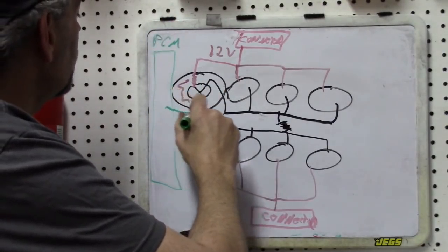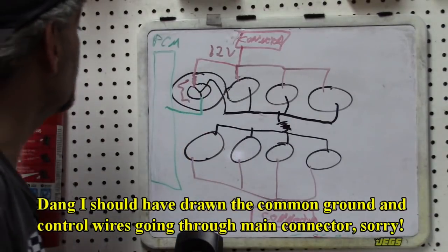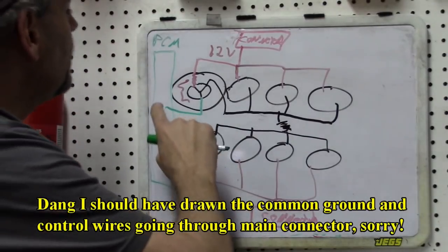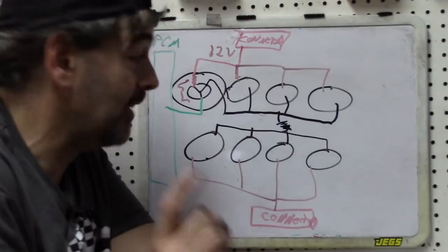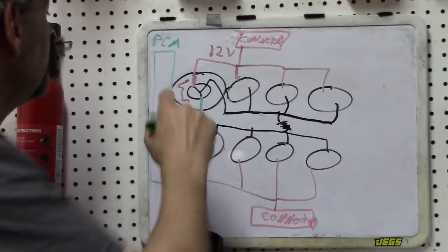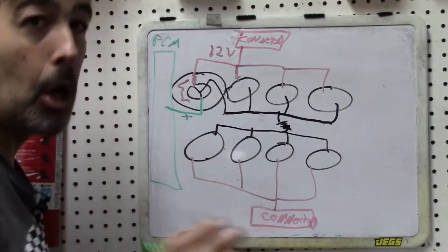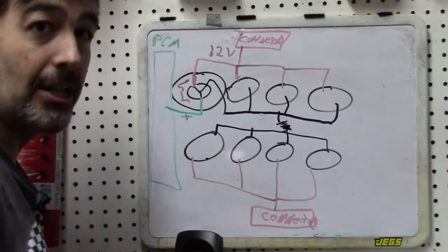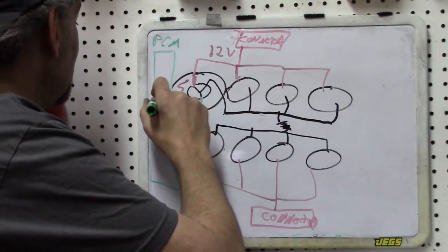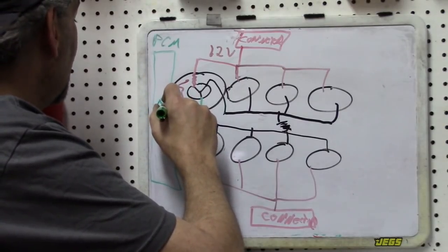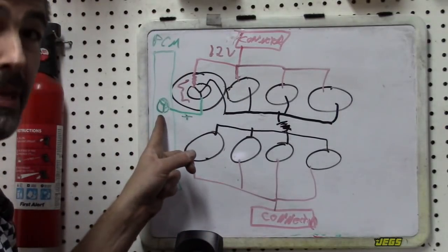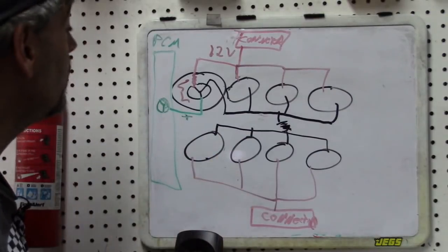And of course, we're going to have control on the transistor base inside the ignition coil in this system. So we don't have ground side switching. It's actually, to be honest with you, positive side switching, pull-up switching, because this is going to feed a small positive feed into that transistor to activate it. So there is also going to be a transistor here as well, where the emitter is going to put that power out. So this is going to be how the PCM controls the firing of the individual coils.